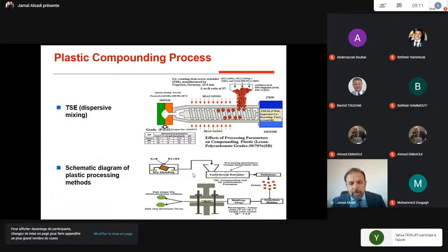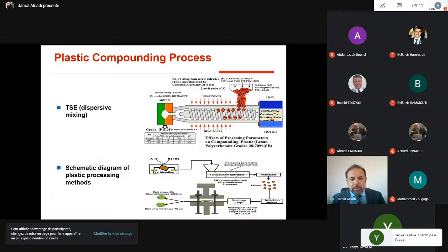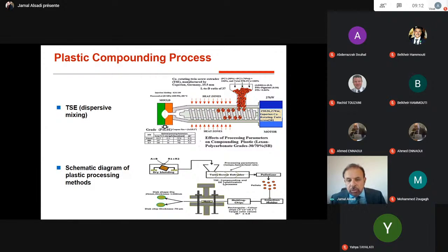As I show here, we are melting the two resins with the additives, pigment, then we put it in the Coperion extruder, then it's blended. After that, we will get the pelletizer, and the pelletizer we will put here in injection molding. Why? To get the color shapes. This piece we run further experimentation on, either for morphology or for viscosity run, to characterize our result and see if we are hitting our target or not.